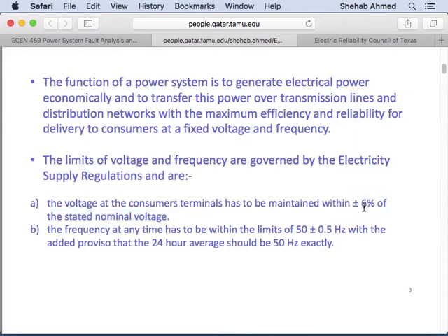And there are limits at the different voltage levels that differ at every voltage level versus the other. So at the distribution level, it may be 5 or 10%. The distribution level is probably the strictest, because these are low voltage pieces of equipment that need to operate within very, very small ranges. But if you're talking about the 200 kilovolt level, things may be a little more lenient, because you're not going to be tapping into the 200 kilovolt level as a consumer, right?